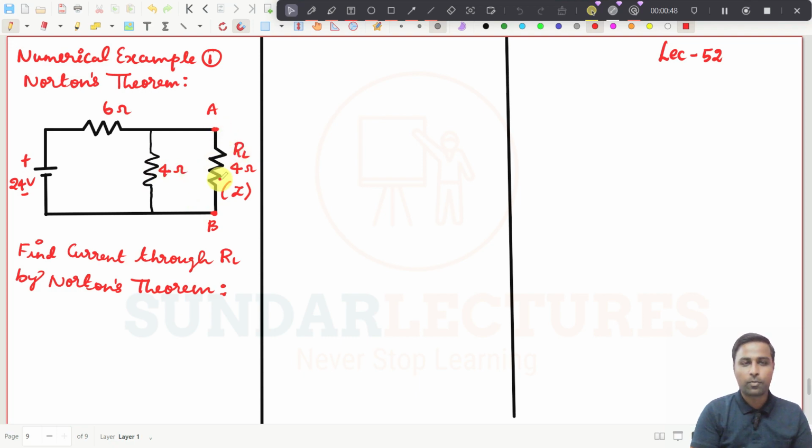See, this is point A and point B, and we have assumed the load to be Z. What is the Z here? It will be 4 ohms, and you need to find the current here, which will be IL. That is the given question: find current through RL by Norton's theorem. This is the linear network. Inside the linear network, we said there can be current sources and voltage sources, and here we have only one voltage source and two resistors present inside the linear network.